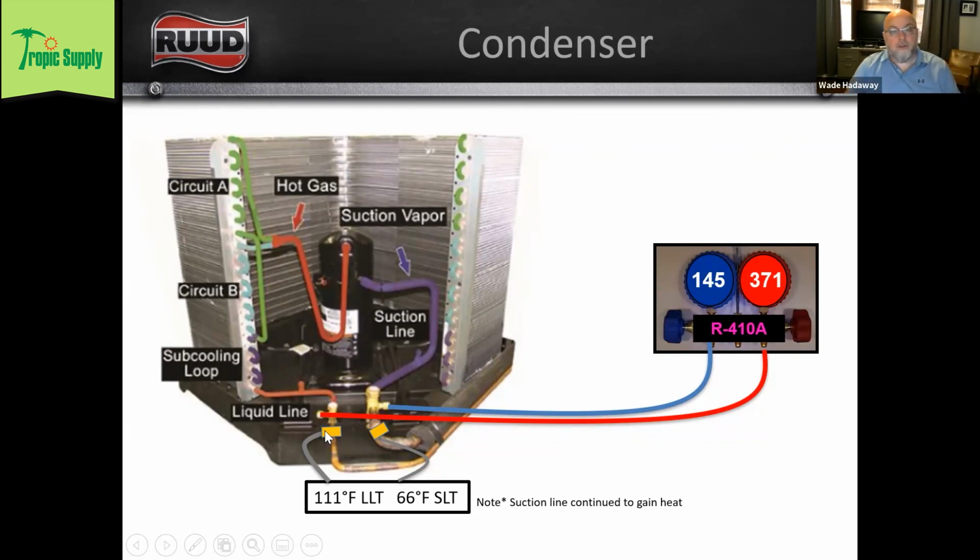Because just like with our evaporator superheat, when we're checking subcooling, we want to know exactly how much liquid refrigerant we have sitting here in our condenser coil. Now that doesn't mean that you can't also check it right at your expansion valve if you're troubleshooting. But as a general rule, that chart is built on checking it right here at the outdoor unit.